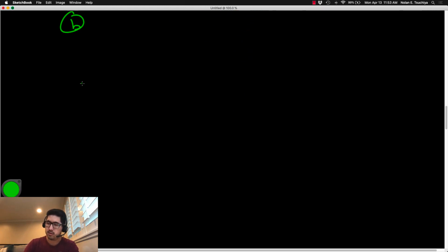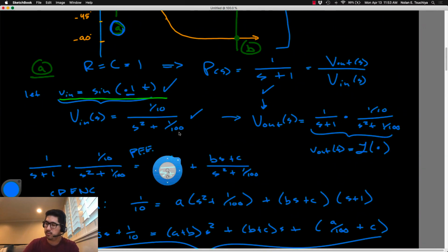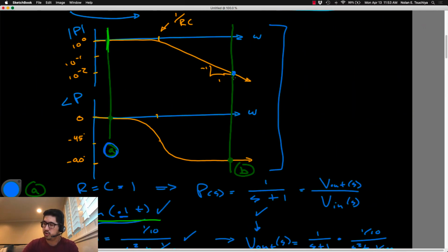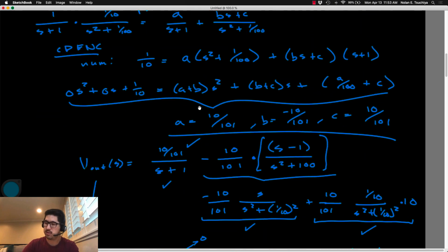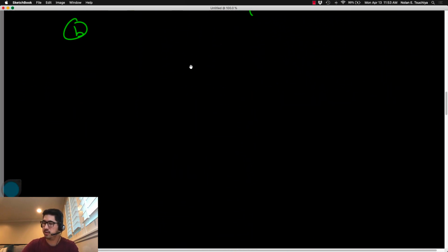If we do a similar thing and look at a higher frequency, remember that at high frequencies, the Bode plot says we should be highly attenuated. That means the output is basically squished close to 0. We should see that at very high frequencies, the signal is really not allowed to pass through, which just means that it's going to be very much attenuated.